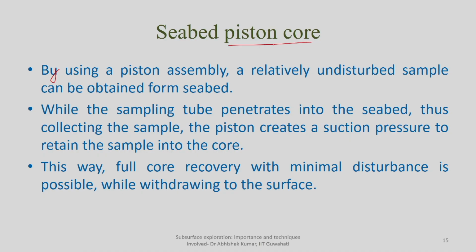However, in this case you are keeping the sample intact, and in order to ensure the sample does not fall down from the sampler onto the seabed, you use some kind of suction pressure. So, this piston assembly ensures the creation of a suction pressure to retain the sample in the core, and that is how the samples collected by means of seabed piston core have almost no disturbance, or minimal disturbance.